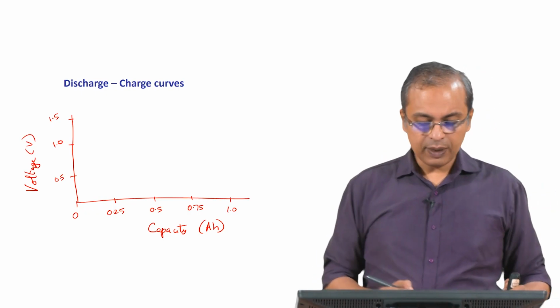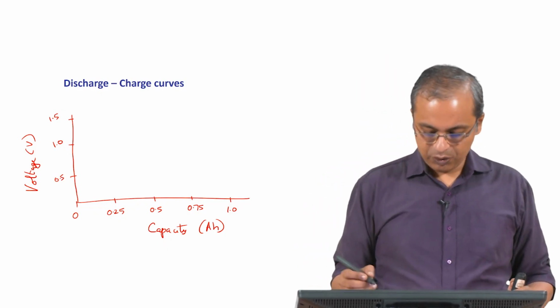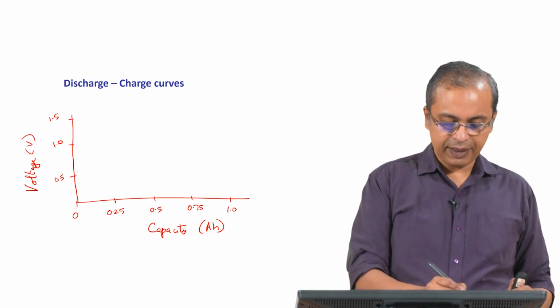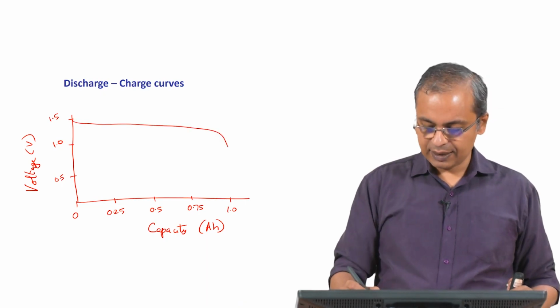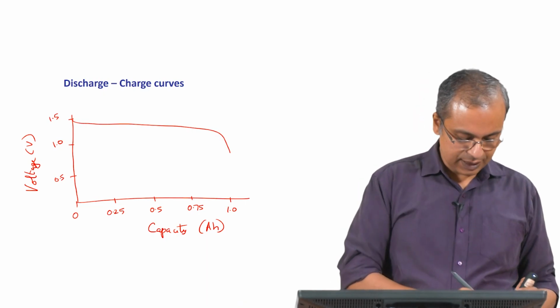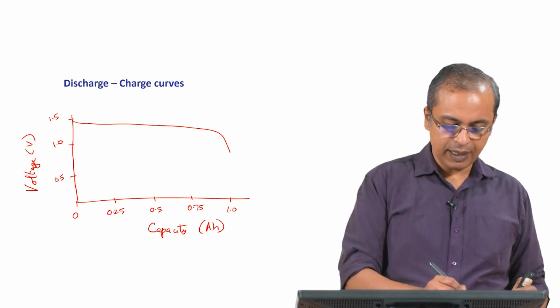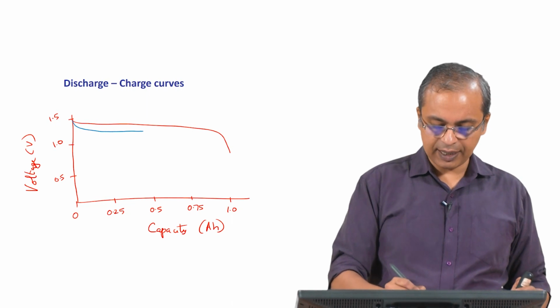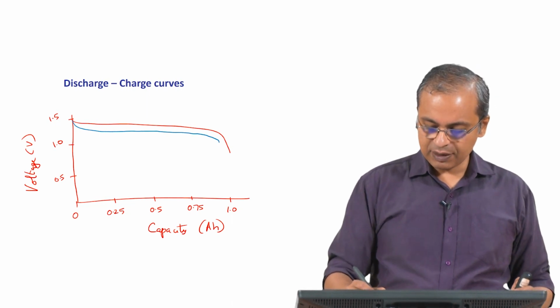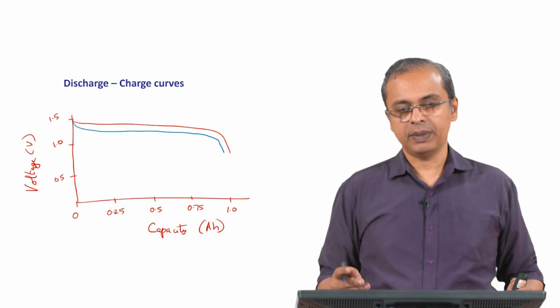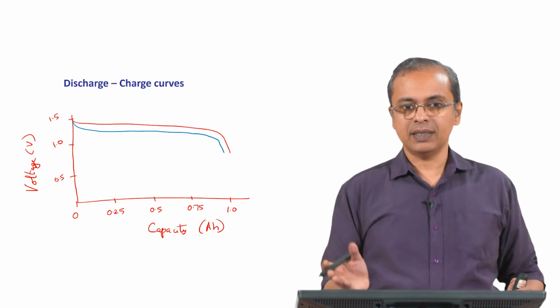Okay. So, now based on the C rate we will have different capacities. Let us say I first draw at some particular C rate and get this capacity, then I draw at some other, higher C rate. Higher C rate will usually mean it will perform a little worse because you are drawing current much faster, and you may not even reach the full 1 C.